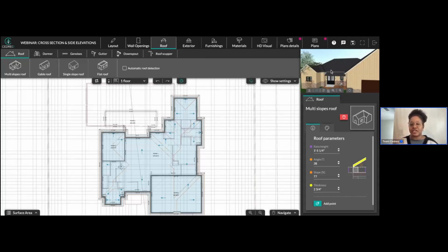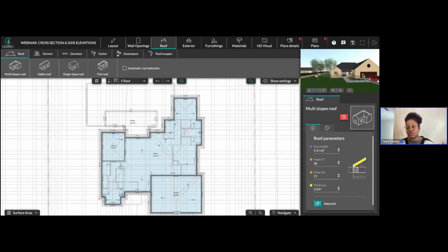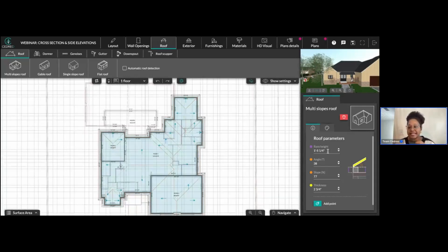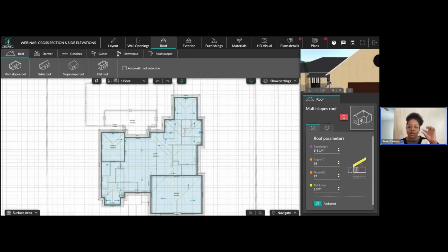And the base height is referring to, as you know, in our roof step, we always recommend, or it's the rule of thumb, to add a level with exterior walls for the roof. So if your project is only one floor, like my project is only a 1-story house, you still need to add a floor above that with exterior walls for the roof. Once you do that and you add the roof, the walls automatically collapse because the walls are used to support the roof. So this base height is referring to moving those walls up and down, right?